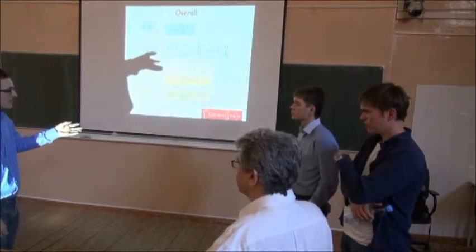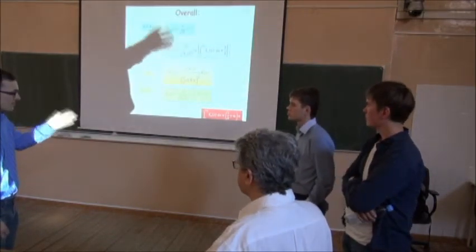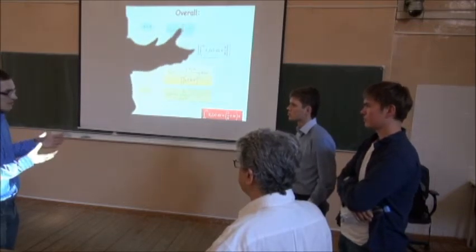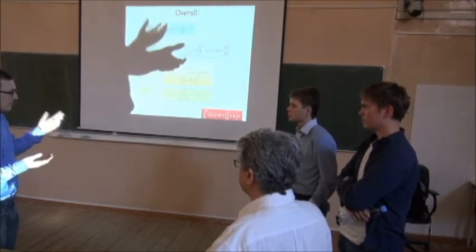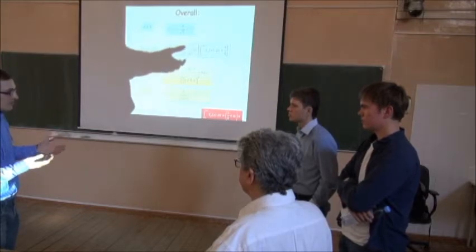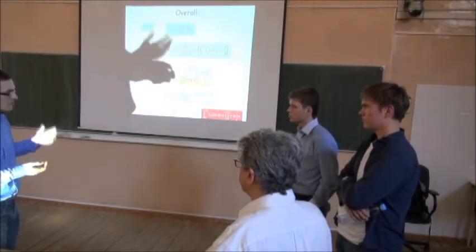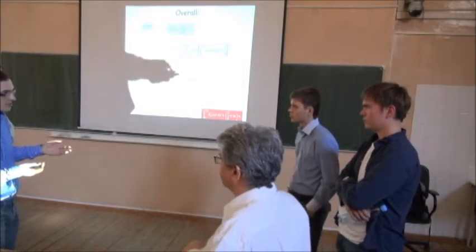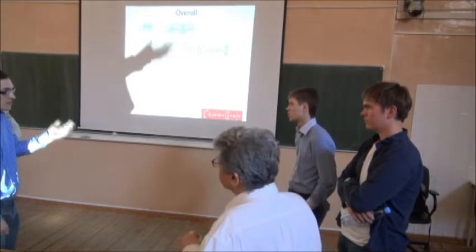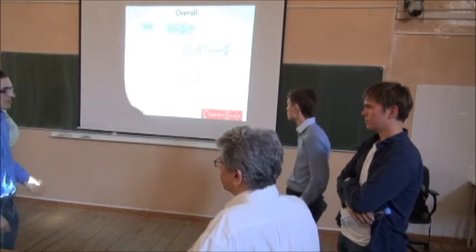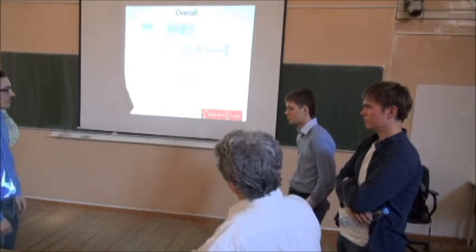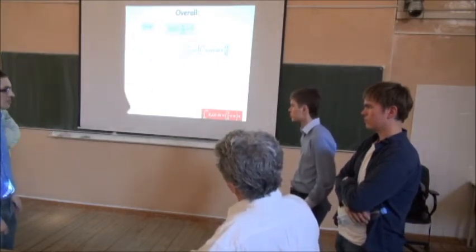Well, actually, in our company, when we get these waveguides, we do m-line spectroscopy, we measure M and N, and then we have some MATLAB program that calculates this. It solves these equations with some approximations.